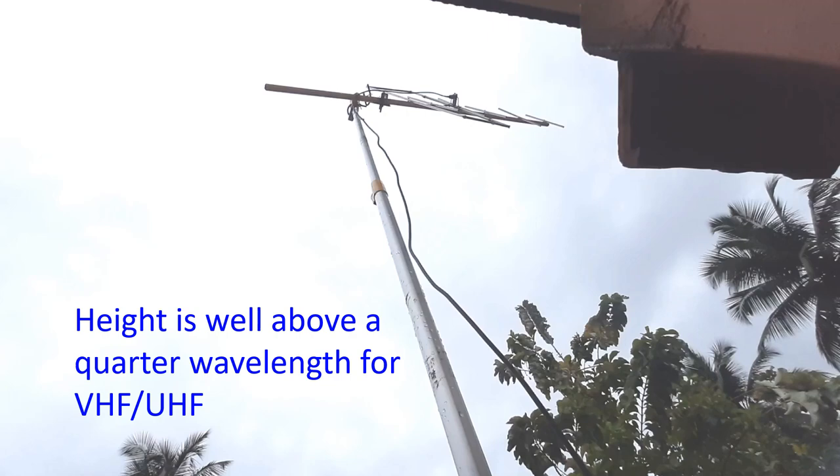Gain of the antenna is determined not only by its physical structure but also by the surrounding environment. Antenna size, elements, and the dielectric constant of the surrounding medium influence the antenna gain. Antenna height is also a very important parameter while considering the efficiency. A minimum height of more than a quarter wavelength of the operating frequency is highly desirable, though often not practical for lower bands.